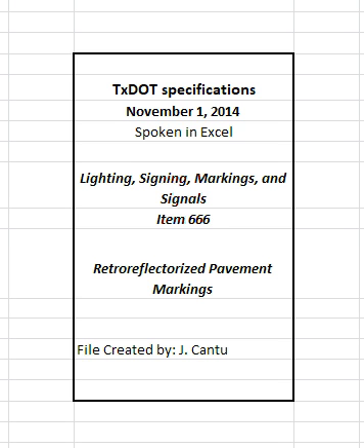Type 2 marking application. Place a 1 square foot piece of clear plastic on the pavement, and weight down the edges. The pavement is considered dry if, when inspected after 15 minutes, no condensation has occurred on the underside of the plastic. Apply markings that meet the requirements of TxDOT 828B, that meet minimum retroreflectivity requirements when specified on the plans, applies to Type 1 markings only.